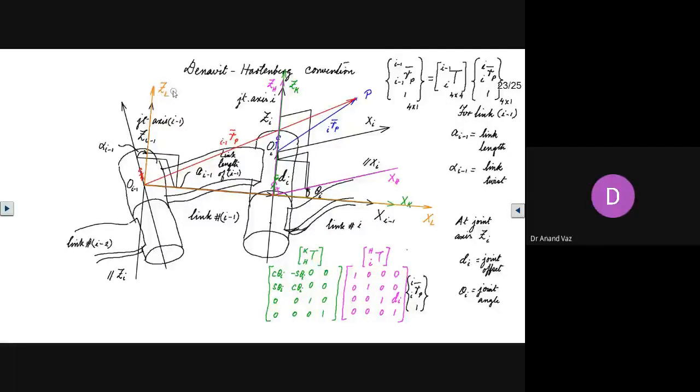Okay. So what is the homogeneous transformation from K to L? The observer in the frame L will see that this frame K, the green frame, is purely translated, as if it is shifted along the x-axis. And you also know how much it is shifted.